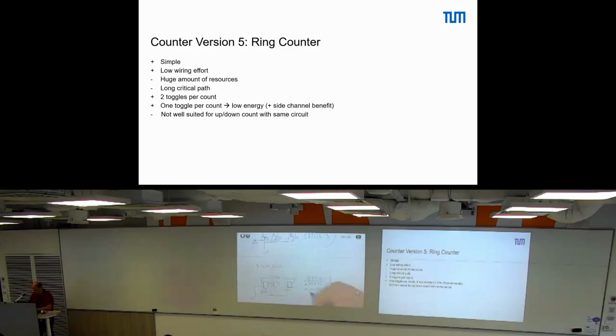Until all of this is a 1, and if this is the case, then the next event will start resetting the stuff until it flows over. It overflows. So, benefits of this compared to the one-hot counter, the ring counter that we had before? What about area, if we want to count to the same number?